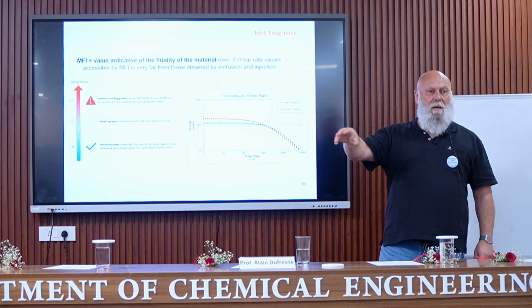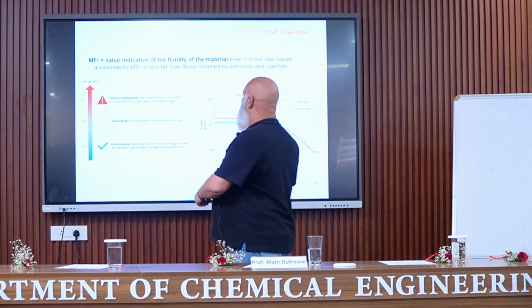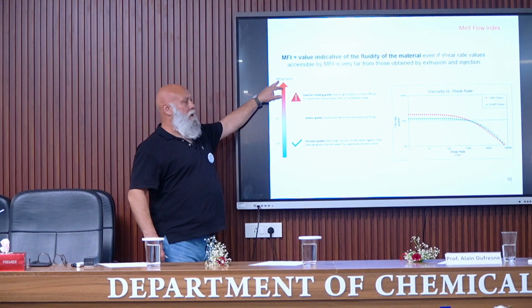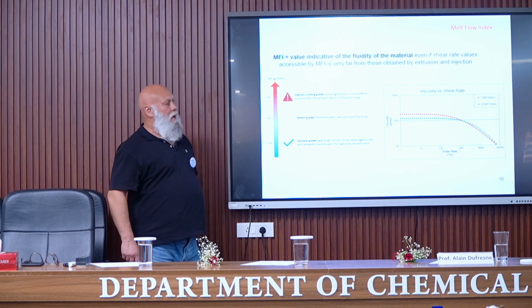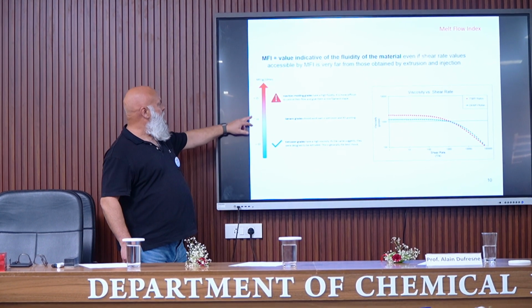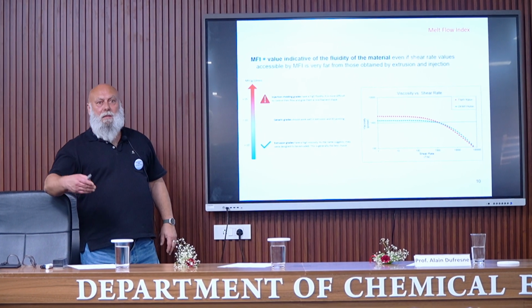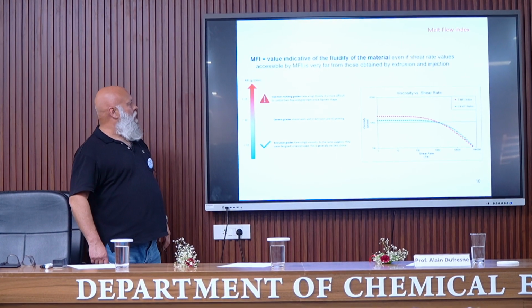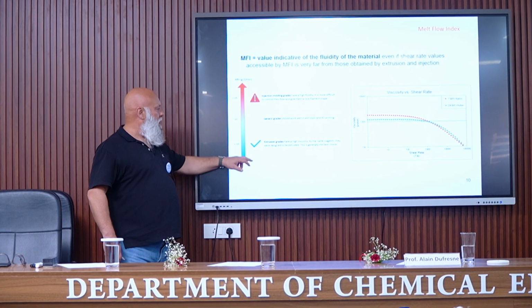You have some indication here. When the melt flow index, in grams per 10 minutes, is around 10, this kind of grade is called generic grade. It can be used for different processing techniques. Now, when increasing the fluidity, so when decreasing the viscosity, usually these polymers are used for injection molding, and lower melt flow index values correspond to what are called extrusion grades.